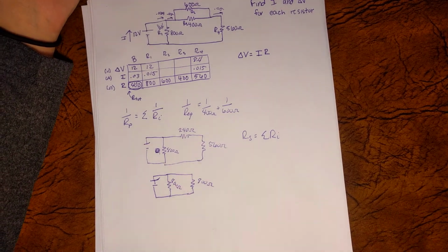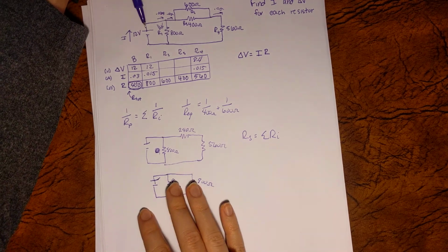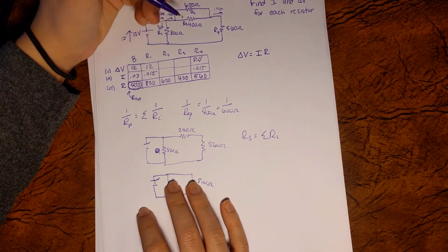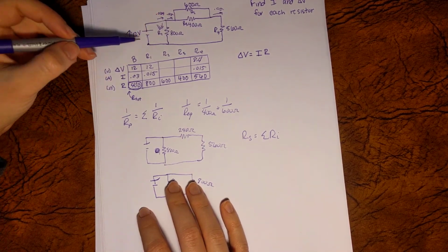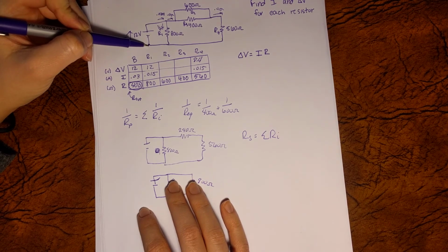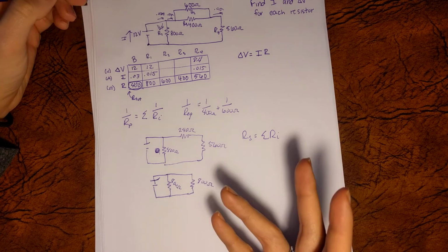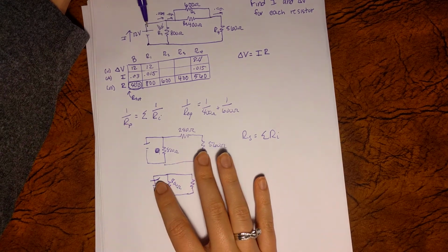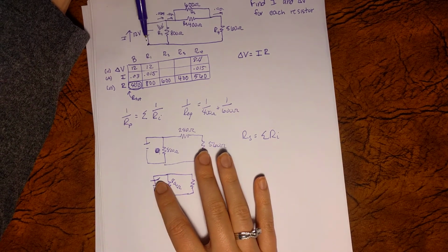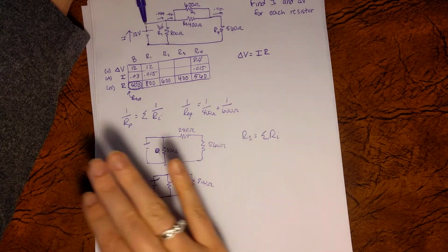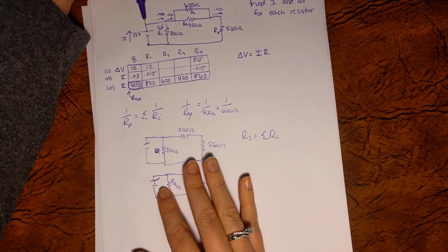Now, let's apply the loop law again. Starting from this corner here, we have to have, let's say, 0 volts because we're coming back to the battery. So we gain 12 volts here, so we have to lose 12 volts overall. Let's take the most straight line path in the way I've drawn this circuit.